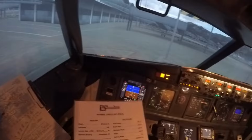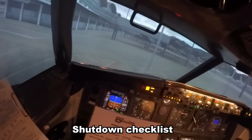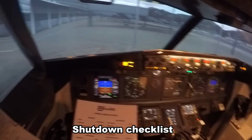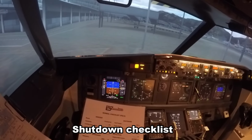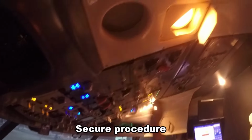Alright, so shutdown checklist, fuel pumps are off, probe heat is off, hydraulic panel is set, flaps are up, parking brake is set, engine start levers are cut off, weather radar is off. Shutdown checklist complete, and we'll just go to our cold and dark state, so we'll secure the airplane.